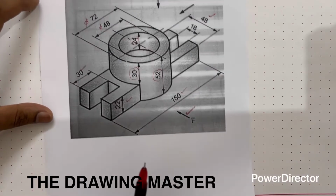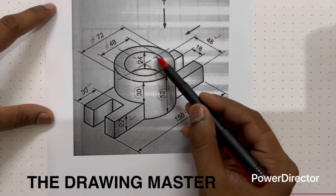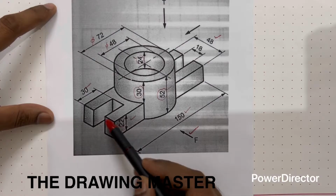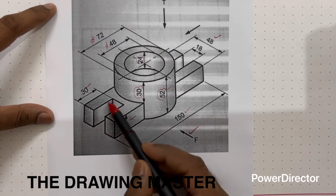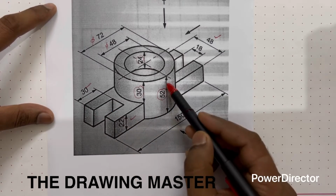So now we have seen all the dimensions here. This is 72, this is 48, this one is 48, this one is 18 from here to here. This length of the slot is 30, thickness of the base is 22 and total height is 52.